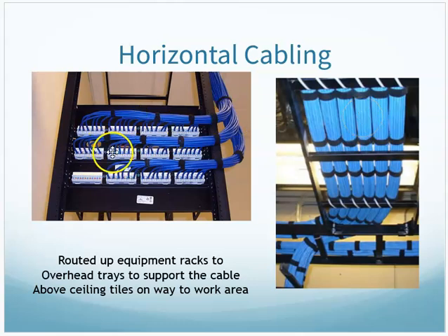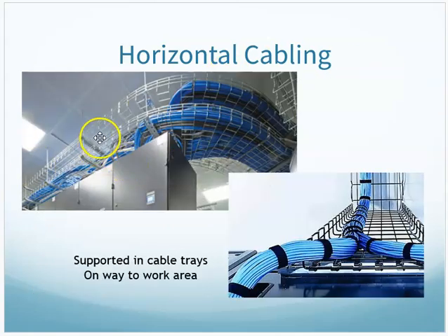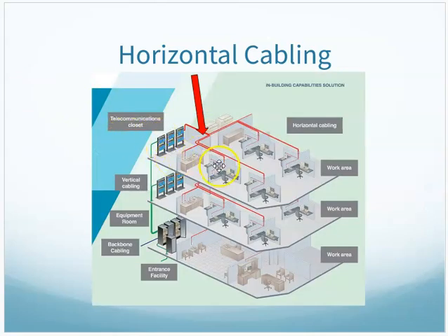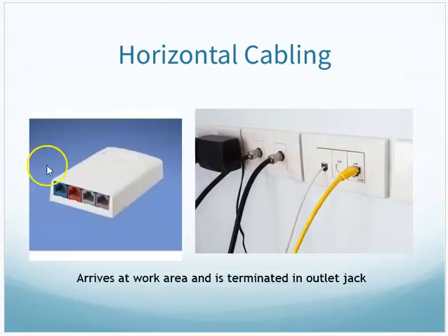Here's your patch panel, your termination, up the rack and through these trays and down the hallway in trays like this, supported, and then it's going to get terminated down the wall and into an outlet in an office. That's what's going to get done.